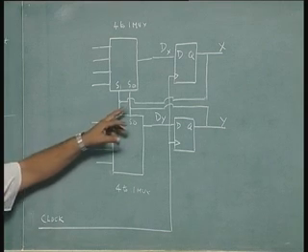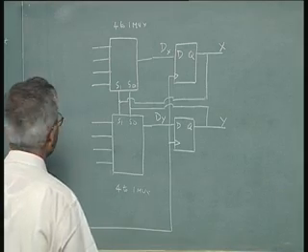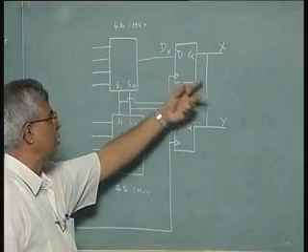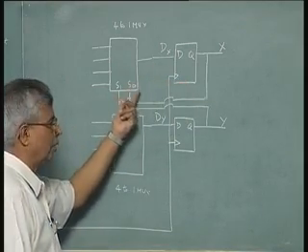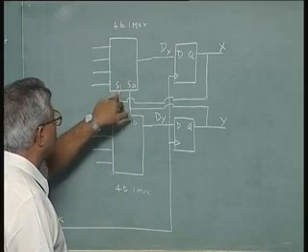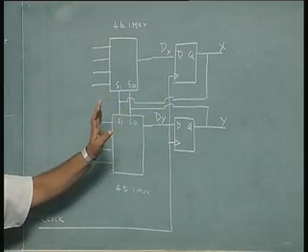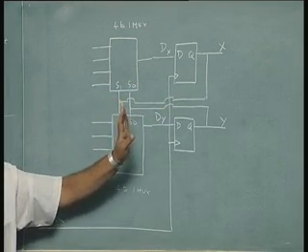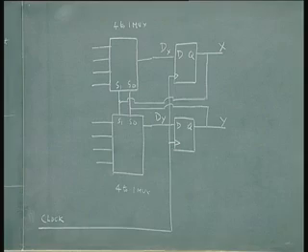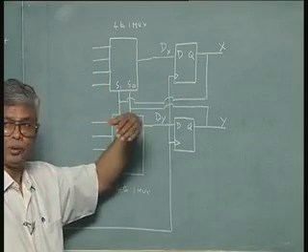Now when we are in the present state, idle state, which corresponds to state variables assignment 0 0, what condition will make it go to 0 1, what condition will make it go to 1 0, what condition will make it remain in 0 0. This is what you have to see. So what we do is we look at one flip flop at a time. We have done this before, I am just reviewing this, so we will do it quickly.